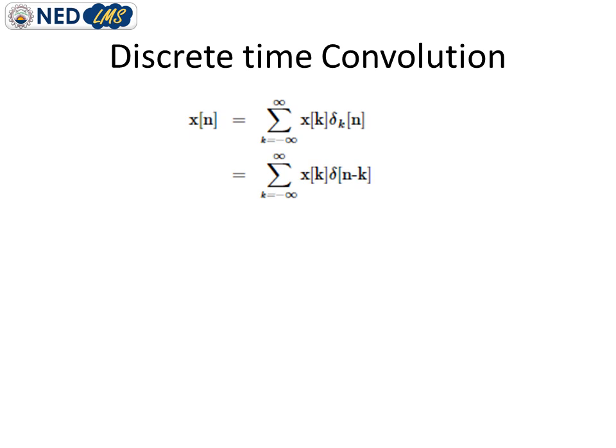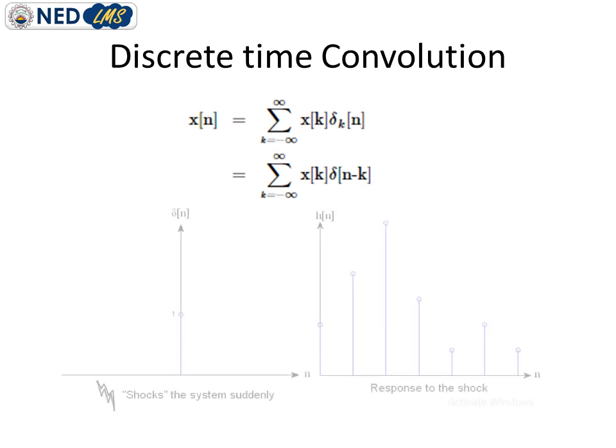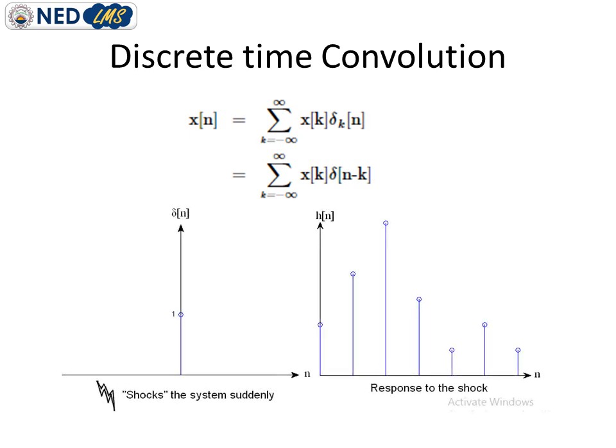So what I have explained to you is generally a mathematical operation or manipulation technique in which you apply shifting and scaling and then add up, or synthesize, the output, and mathematically we use the term convolution for this operation. As we are dealing with discrete time signals, this is the convolution sum, but if we are talking about continuous time signals, it will be termed the convolution integral.